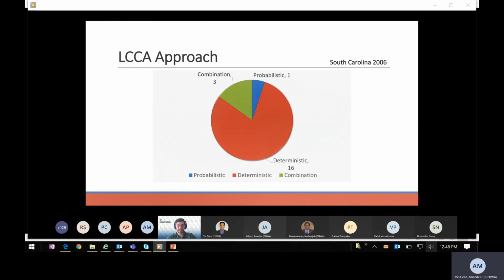Through a sampling process, any given alternative values are randomly drawn from input variable distributions and are then used to compute single forecasted output values. Now, fundamentally, what you need to know is that the probabilistic LCCA accounts for uncertainty and variation in individual input parameters by producing a probability distribution of present values for each project alternative in analysis.